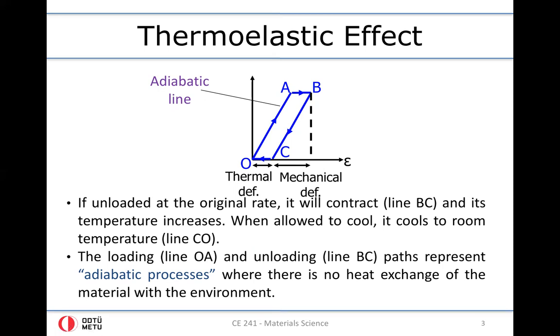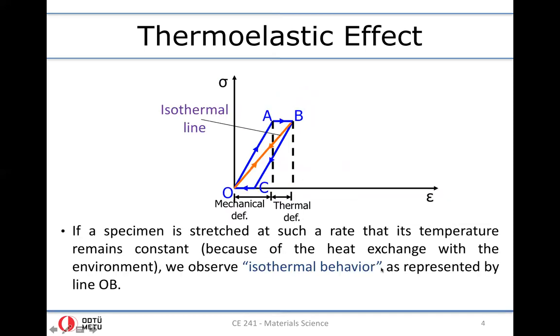These are processes so fast that the material doesn't have any time to exchange heat with the environment. If the specimen is stretched at a rate that is slow enough, the material will always have time to exchange energy with the system. Therefore, we don't observe any temperature changes. In that case, what we obtain is the isothermal line, which represents the elastic behavior.